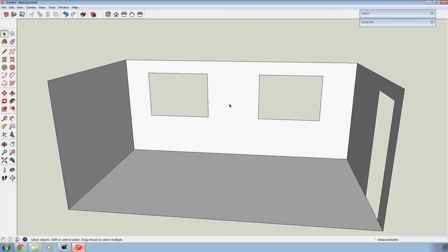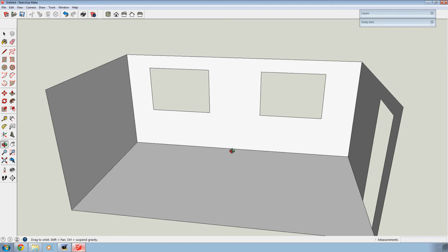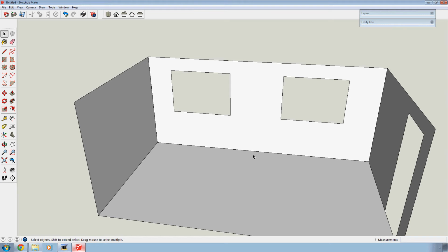In this particular kitchen, the clients already have a relatively new range cooker, and it's 900 wide, and we'll assume it's 915 high. I mean, they usually have adjustable feet, and we'd obviously want to adjust it to be the same height as a worktop. And being a standard machine, it'd be about 600 deep. So I'm going to draw in that range because it's in a fixed position. You'll see why in a moment.